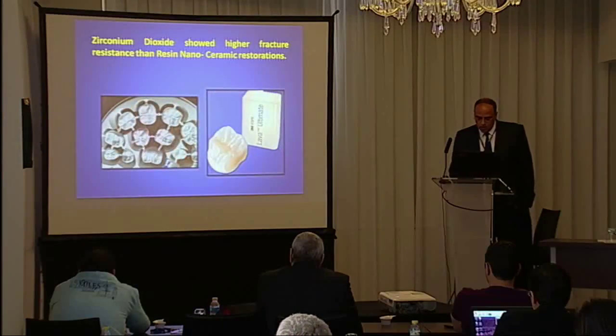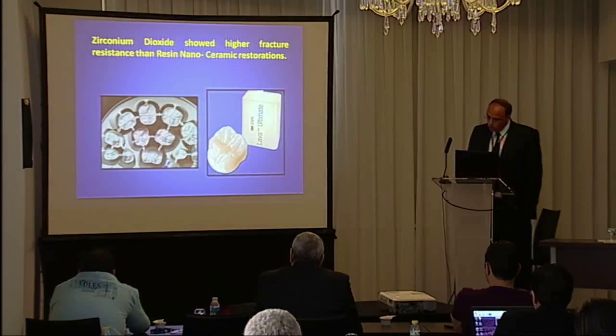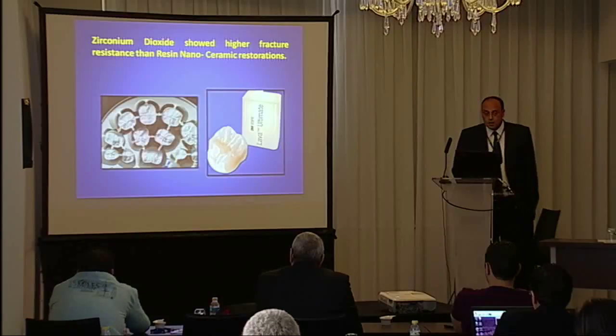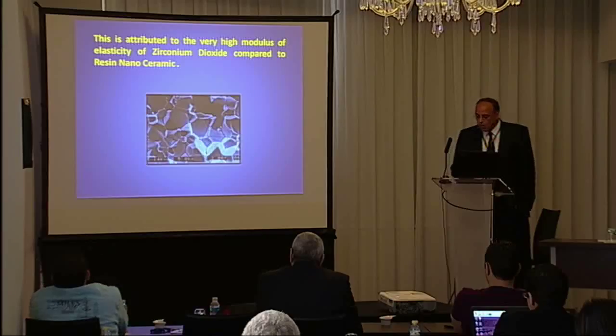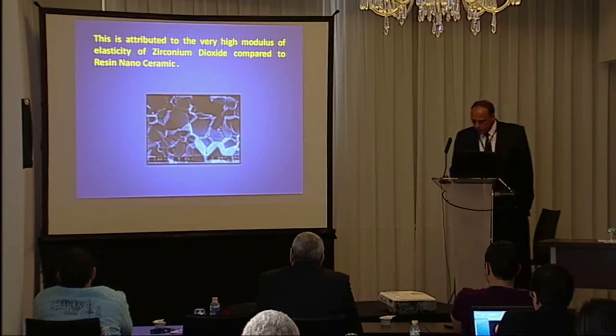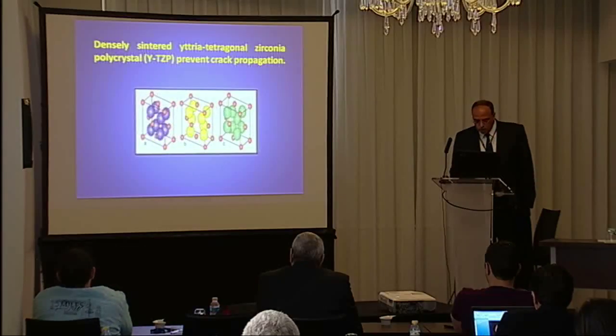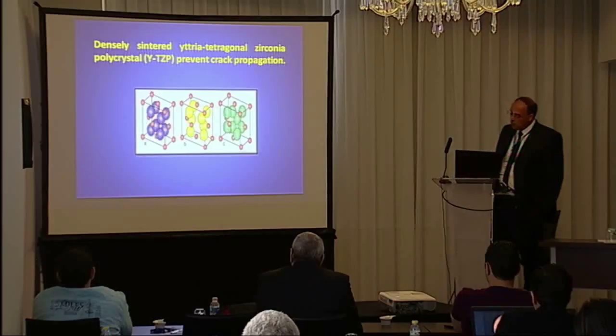Discussion. Zirconium dioxide showed higher fracture resistance than resin nano-ceramic. This is due to its very high modulus of elasticity compared to resin nano-ceramic. The densely sintered yttria tetragonal zirconia polycrystal prevents crack propagation.